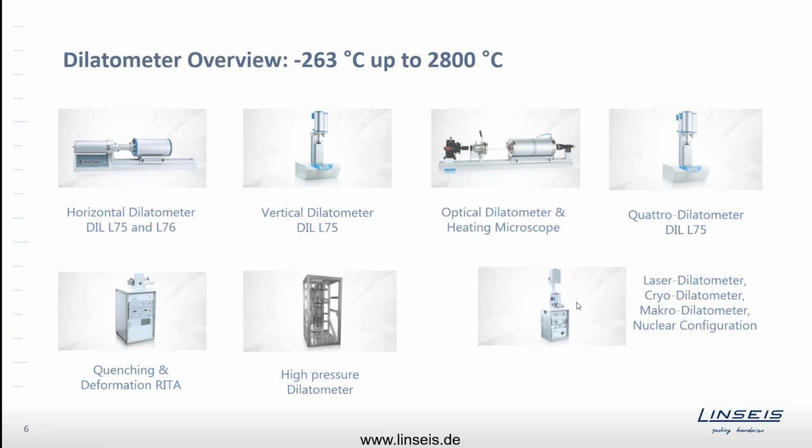Of course, there are multiple different ways to build it, set it up. The drawing you just saw fits to the standard horizontal dilatometer you see up here. It's called DIL 7576, which is our basic series. This series can be used horizontal, like you see on this first picture. It can also be used vertical. I will explain the difference and the advantage and disadvantage on the next slide. Just keep in mind that the standard configuration is available as a horizontal or vertical setup. These are our standard push-rod dilatometers, and besides that, we have different special versions.